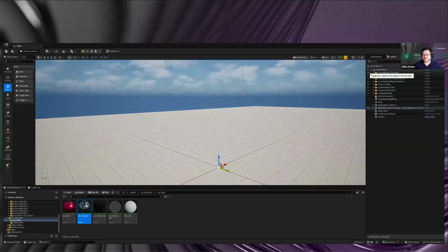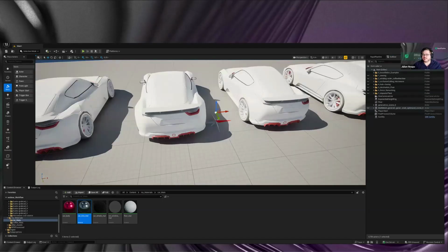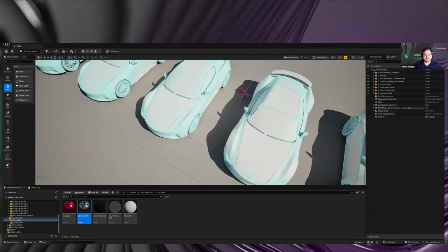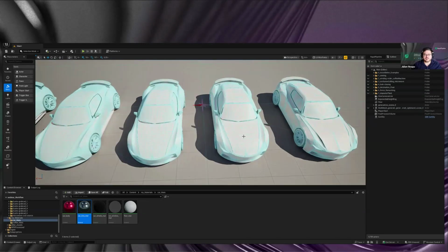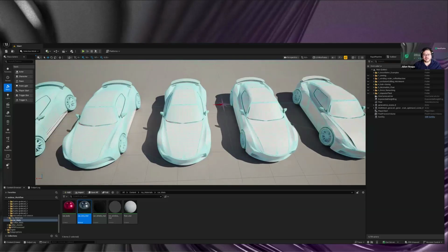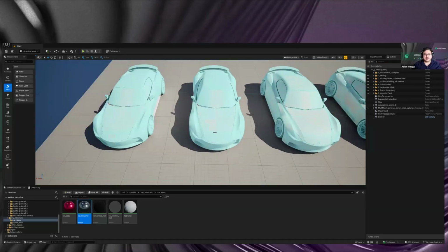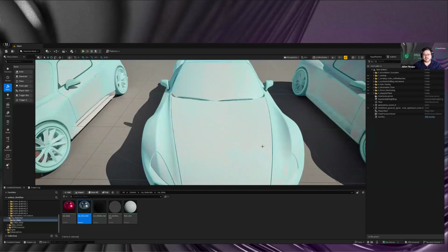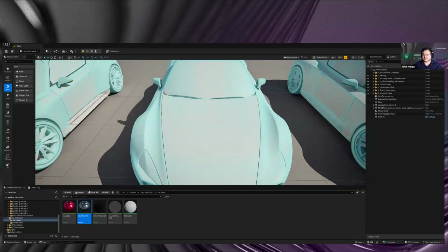And let me just unhide the actual demo version here for the cars. Let me go back into the wireframe mode. Here you can see the different imported versions of the car from the slides, where we go from extra coarse all the way to extra fine. And on the left side, I even have versions with a custom tessellation where I went even more fine-grained in terms of the surface deviation, with even less surface deviation allowance, and then tessellating it even finer.